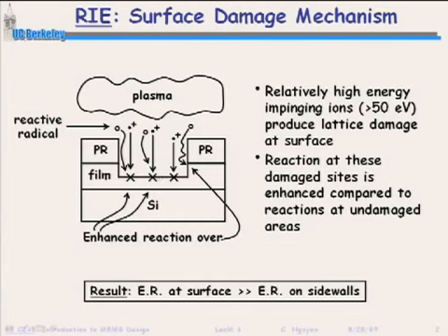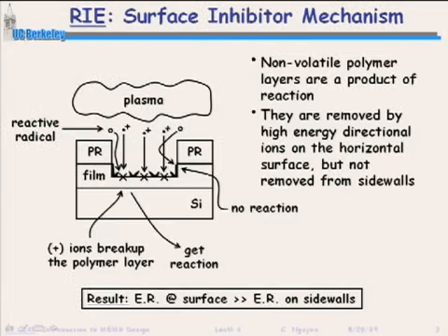There's another mechanism, however, that can be used, and that is if you include among the gases in the plasma carbon type species, you actually can do things like grow polymers over your films. And so that's one other way to do reactive ion etching.